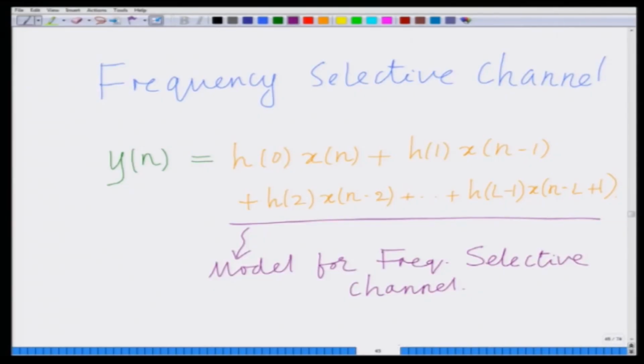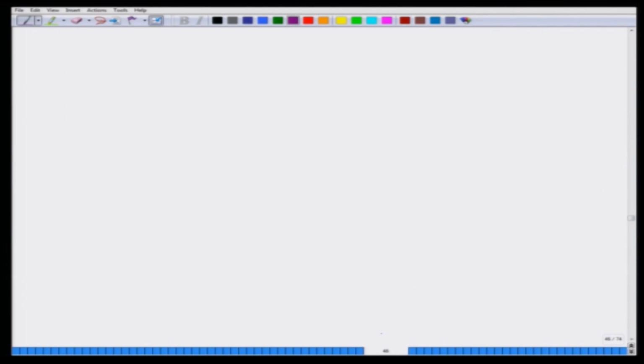So, in the time domain, this channel has inter-symbol interference, which is the same thing as frequency selective channel or frequency selective fading in the frequency domain. Therefore, this input output received symbol model with inter-symbol interference represents a frequency selective channel, all right. And now we are going to consider this frequency selective channel in an OFDM system. As we said previously, in the OFDM system we generate the transmit signal using an IFFT operation. So, let us do the following.